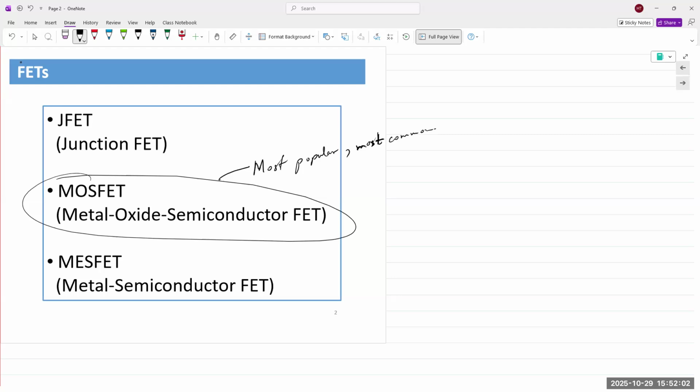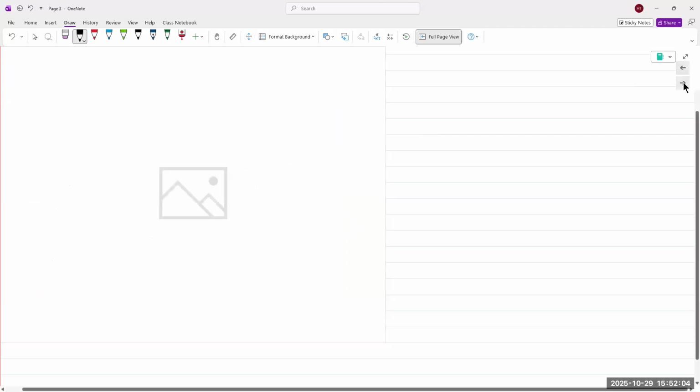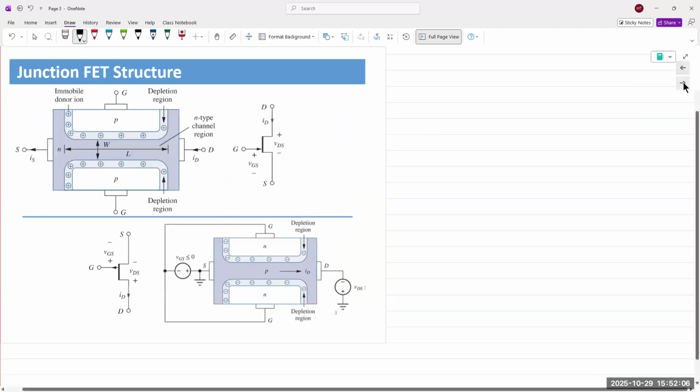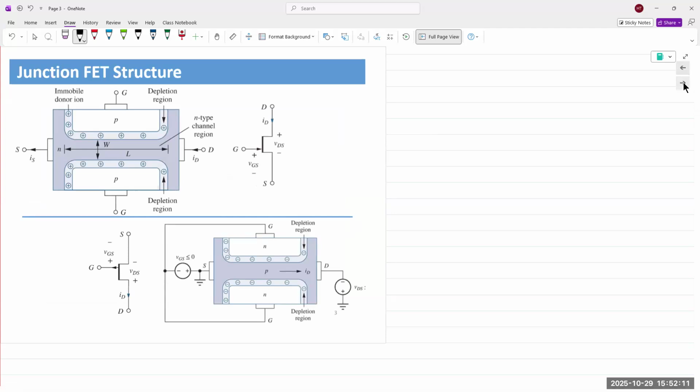Okay. But anyway, the JFET is something I do right around here because lab 6 is about JFET characteristics. Okay. So JFET is a 3-terminal device. It's a 3-terminal device that has 2 PN junctions, but those 2 PN junctions are not back to back. They are not a sandwich structure. Okay. In a BJT, a bipolar junction transistor, they are back to back structures. FET is a very different kind of fabrication structure.